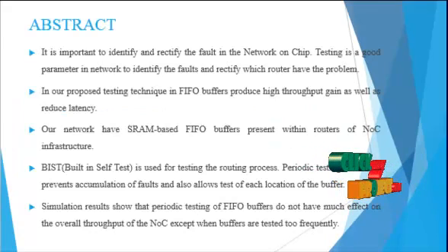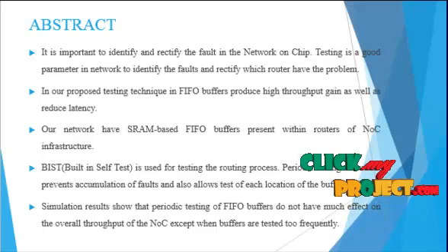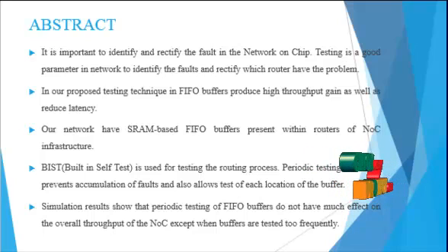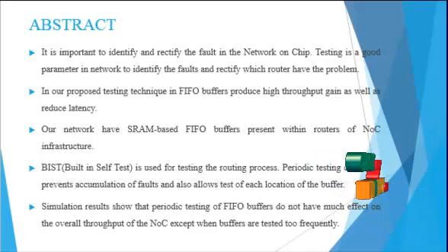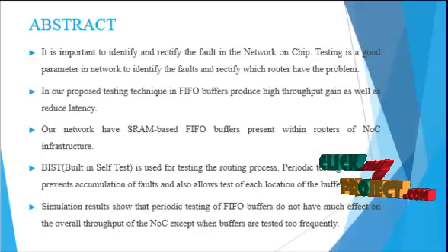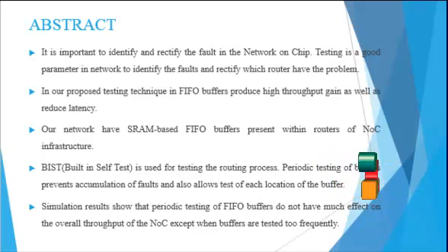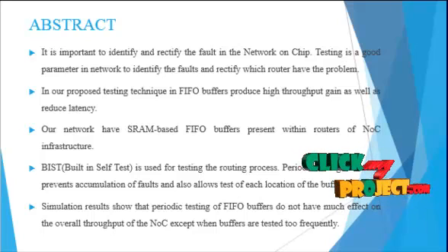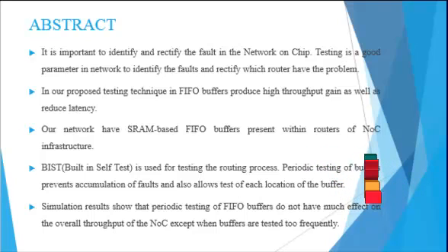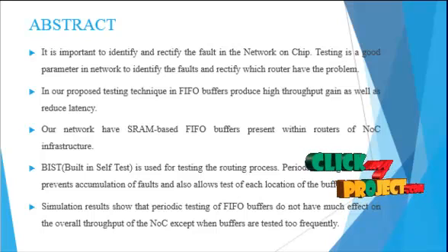Abstract. This brief proposes an online transparent test technique for detection of latent hard faults which develop in first-input first-output buffers, that is FIFO buffers of the router, during field operation of NoC. The technique involves repeating tests periodically to prevent accumulation of faults. A prototype implementation of the proposed test algorithm has been integrated into the router channel interface, and online test has been performed with synthetic self-similar data traffic.